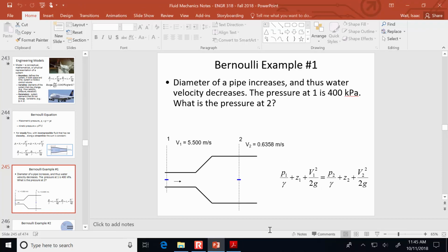And the reason why is that we're assuming that there's no energy lost due to pipe friction, but in reality, like in a real pipe network, let's say we've got a long pipe and we observe the water is going from one direction towards another spot. Why does the water go from 1 to 2? It's because at 1 the pressure is higher, and at 2 the pressure is lower. Like, water flows downhill. We've all seen that. We know that.